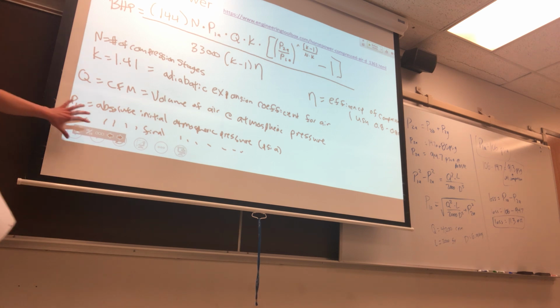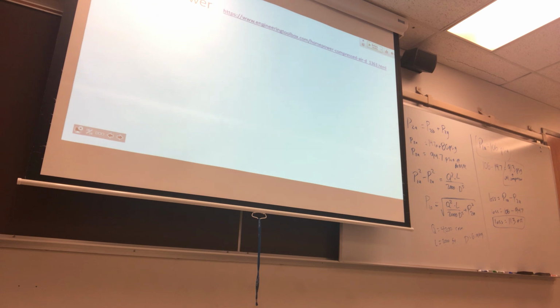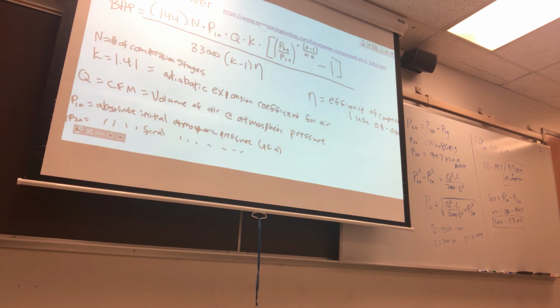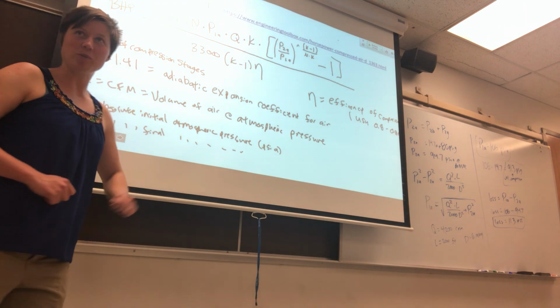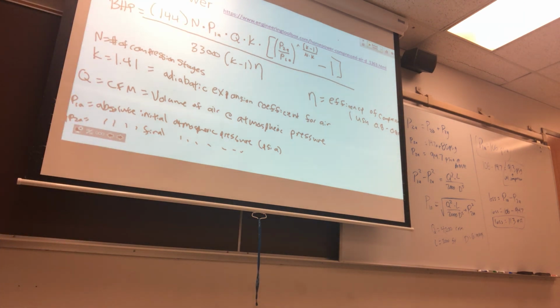Sweet, so we have all these terms, we have this chunky equation, but we can double check ourselves with what we have online. Engineering Toolbox is a great use where you plug in your variables. You're like, okay, I have this CFM of my pump and I've read these pressures. I know my efficiency is 0.8. You plug it in and it gives you your brake horsepower. It's really great. Great tool to have.